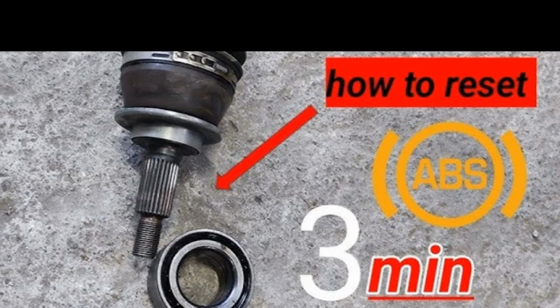It generates an analog AC wave. A digital sensor produces a square wave signal, and some can even detect the direction of movement, forward or reverse. 3. Detection of steel teeth or magnets. Typically, the sensor reads the steel teeth that pass in front of it as the wheel rotates. In some cases, a series of magnets may be integrated into the bearing's grease seal, and the sensor is designed to detect these magnetic pulses.